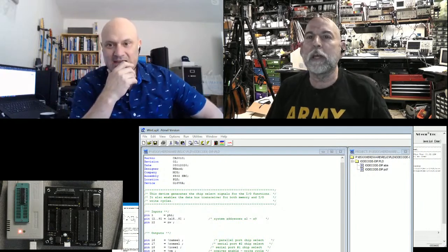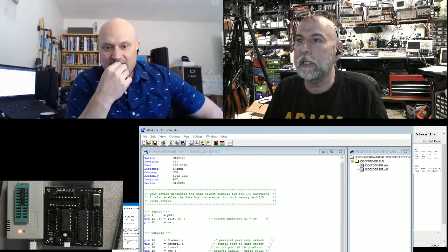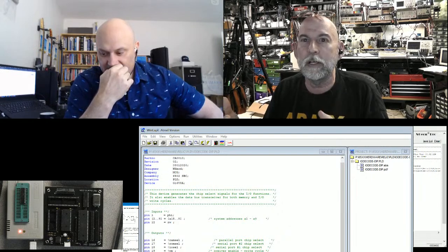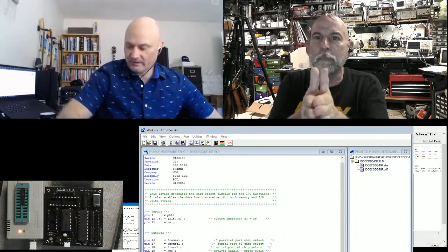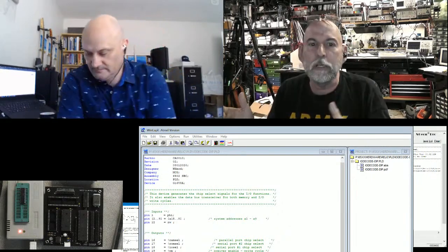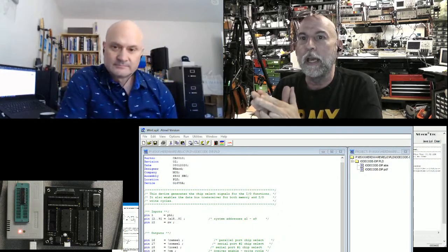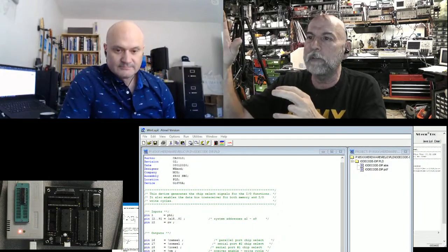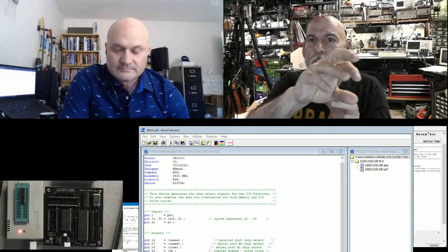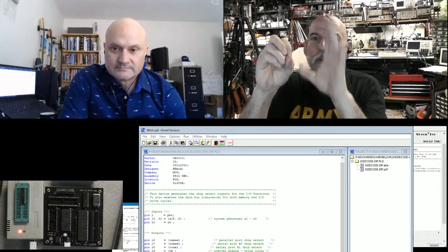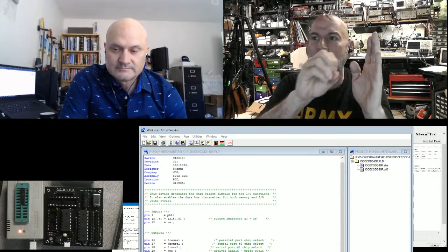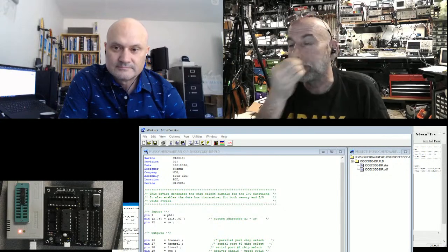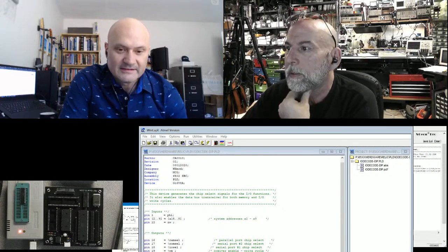Right. And so you start with a higher frequency clock, which is very key. If you want to do something at 1 megahertz, but you want to keep clocking your minterms, you start with a 16 megahertz clock or something. And you're absolutely right. Rather than have logic go through more logic and start to race, you go through a chunk of logic, flip-flop, chunk of logic, flip-flop, and it's called pipelining. Yeah, exactly.